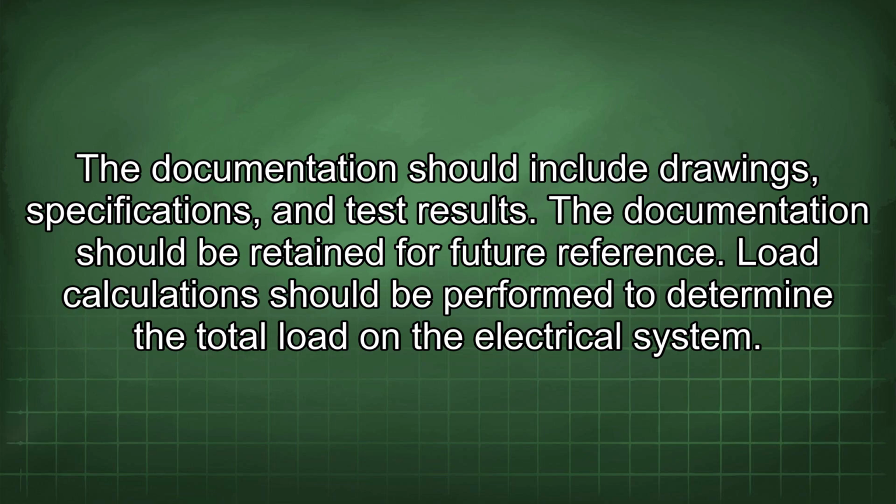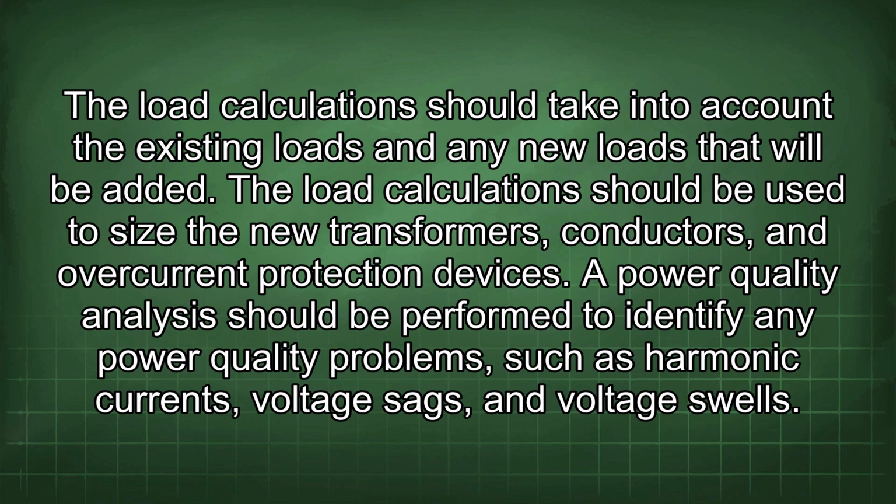Load calculation should be performed to determine the total load on the electrical system. The load calculation should take into account the existing loads and any new loads that will be added. The load calculation should be used to size the new transformers, conductors, and overcurrent protection devices.